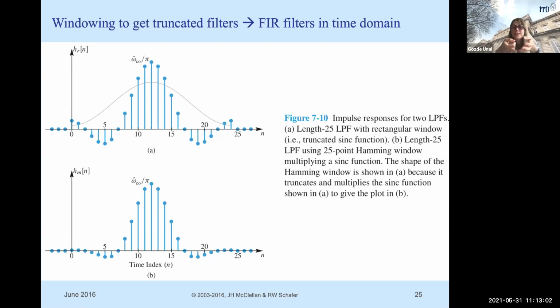All of a sudden, why am I talking about these? I'm talking about these because I'm saying now practical filters. I mean, we were talking about an ideal low pass filter, sinc, but it's not realizable. It's an infinite extent signal. Now practically, how can I obtain a low pass filter?